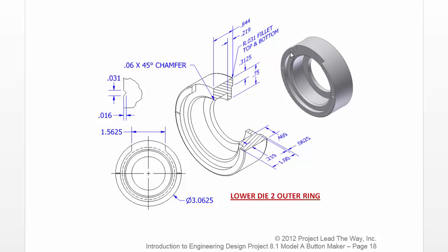Now the issue is that this outer lip here actually is not existent on the top 1.5 inches or so of this. So this section view kind of shows what it looks like without that upper lip, and this one shows it with. But I think it would be easier to make the whole thing with the upper lip and then just remove the 1.5 inches worth of it here. So that's what I'm going to do.